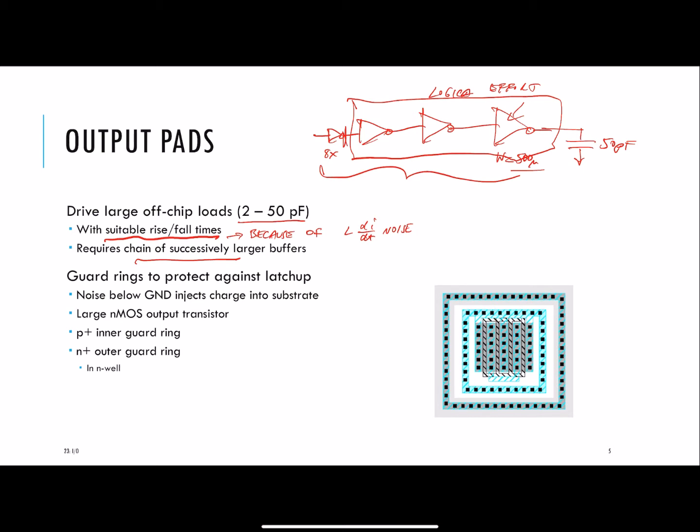It's noisy from the point of electrical noise. It's sort of noisy in the way of mechanical stuff going wrong, if I can call that noise. But there's a lot of stuff that can go wrong there. So basically what you want to do is isolate these structures with lots of guard rings.